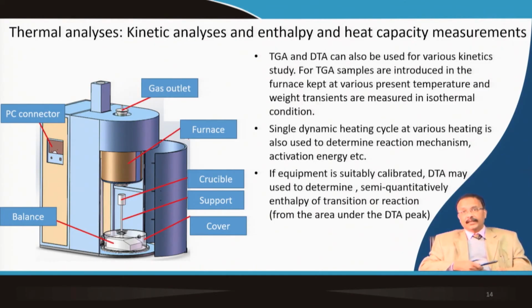Alternatively, a single dynamic heating cycle at various heating rates can also be used to determine the reaction mechanism, and from this one can precisely determine the type of nucleation and growth, whether it is Avrami type or some other type, and what their activation energy is. This can be very precisely known by this kind of kinetic analysis.